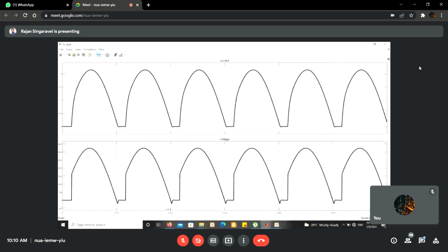But this is not applicable for the RMS, because RMS does not carry the quality of the voltage. But for average voltage, with respect to the R load condition, the RL load will have a lesser average DC voltage for the same firing angle and the same supply voltage magnitude.